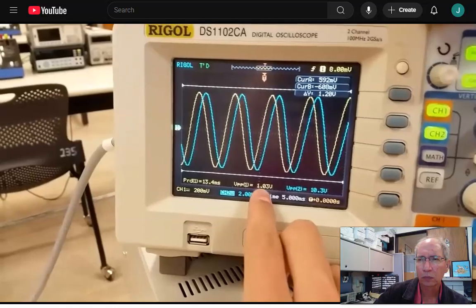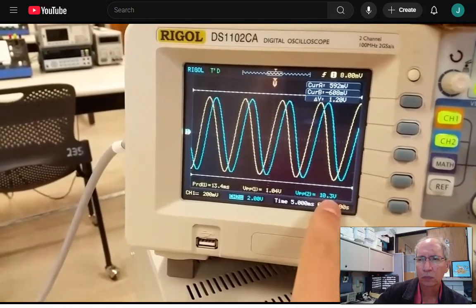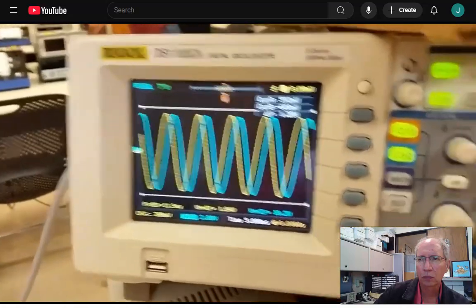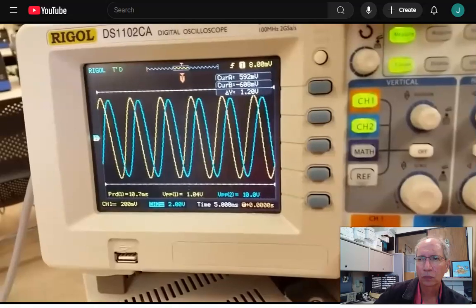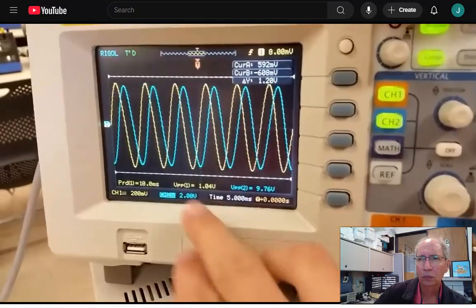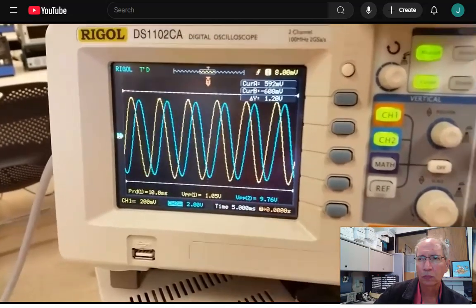Since it's at 75 Hertz, the gain is 1, but also it's amplified by 10. As I switch the Hertz up, I'll go to 100 Hertz. It's about 0.9. That was our design specs, so it's about 0.9 amplified by 10.